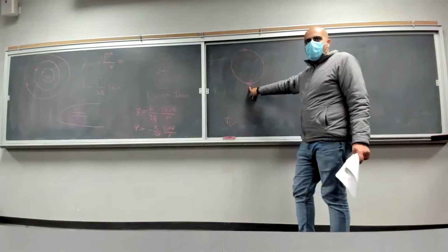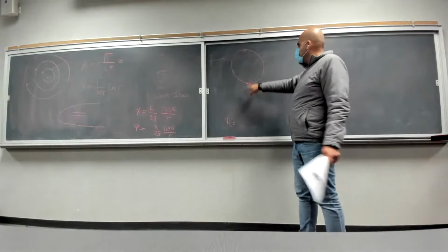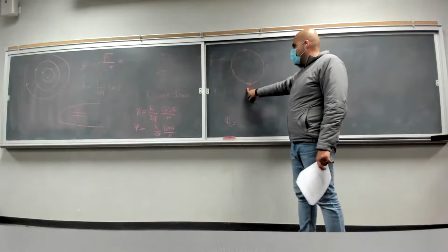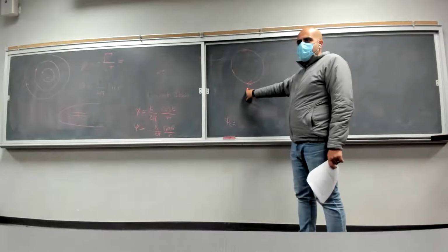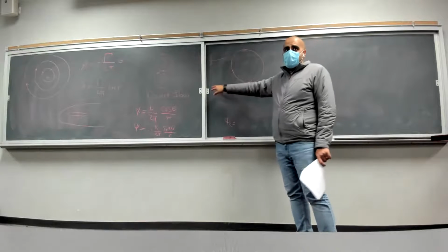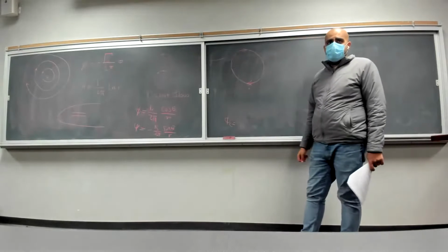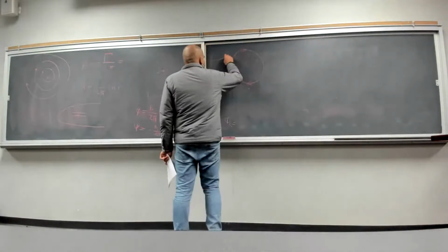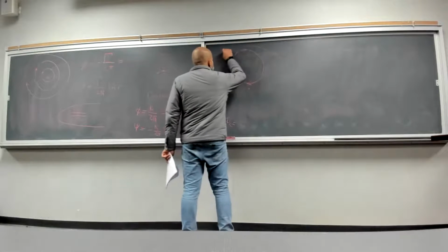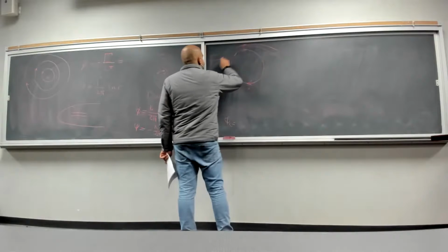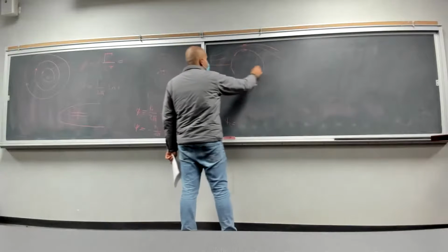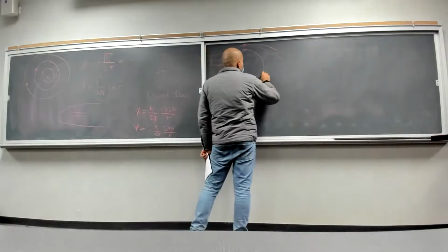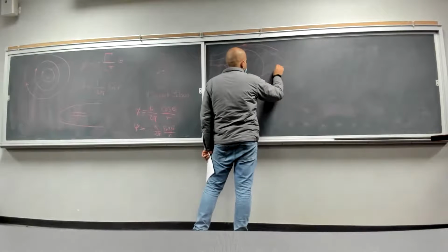And the velocity on the bottom surface, at 3π/2, at 270 degrees, is going to be less because it is being subtracted from the uniform flow velocity, right? Okay, which essentially means that your stagnation points for this specific flow are going to move down.